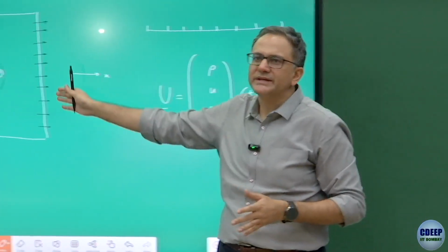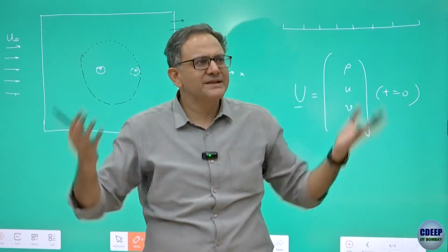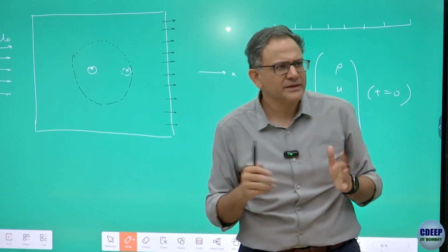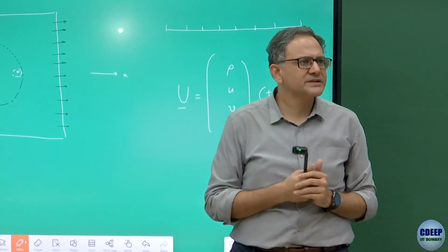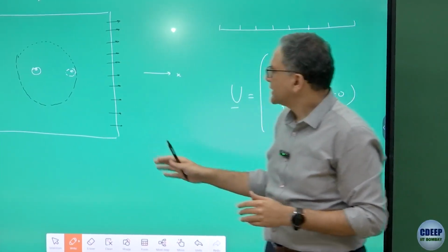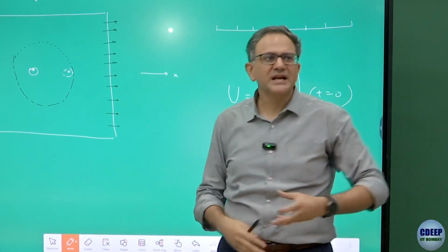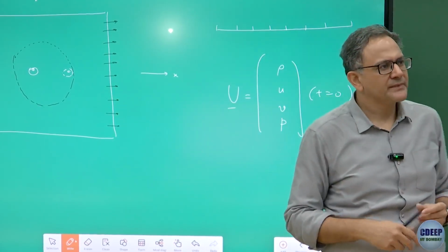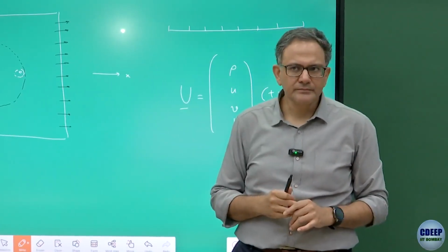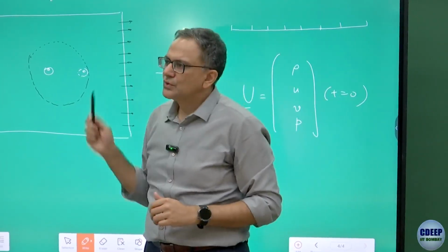This is not a real boundary, this is my artificial boundary, because I don't have the capacity to imagine a larger grid or to solve for a larger grid. You have to choose your domain based on your computational resources, and it's always finite. So you will have a certain boundary to your computational domain which should be transparent to these waves: acoustic, vortical and entropic. And the other three boundaries have to pass only the acoustic wave.